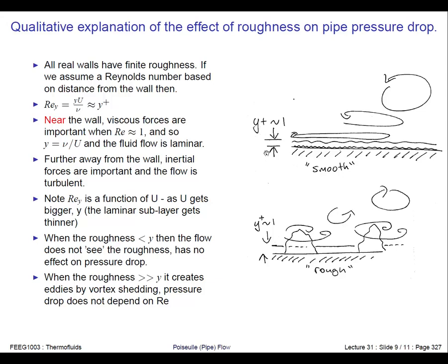And the turbulence out here is driven by what's coming into the pipe and the state of the flow. It's not actually driven by the roughness itself. Then you take the opposite case, the fully rough case, where your roughness elements are much larger than the laminar sublayer. So your roughness elements are protruding into the turbulent flow. They're not in the laminar region anymore.